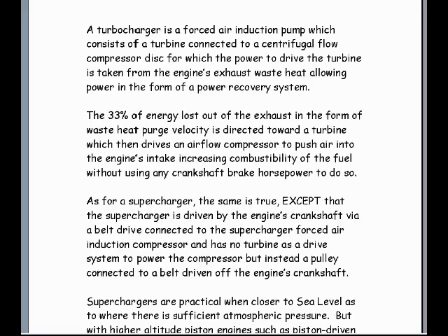The 33% loss out of the exhaust in the form of waste heat purge velocity is directed towards a turbine, which then drives an airflow compressor to push air into the engine's intake, increasing combustibility of the fuel without using any crankshaft brake horsepower to do so.